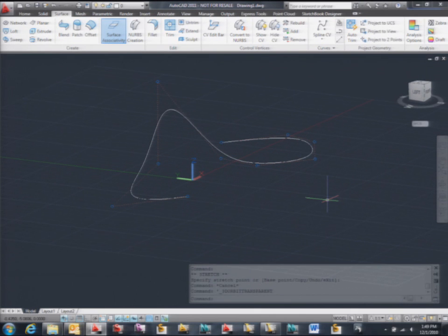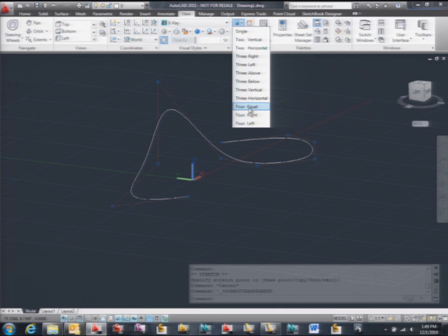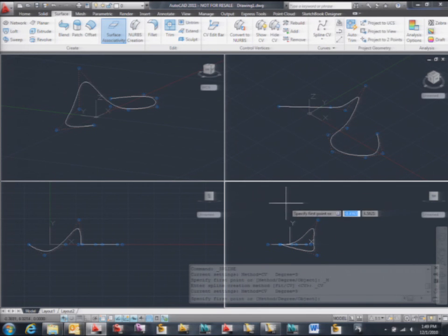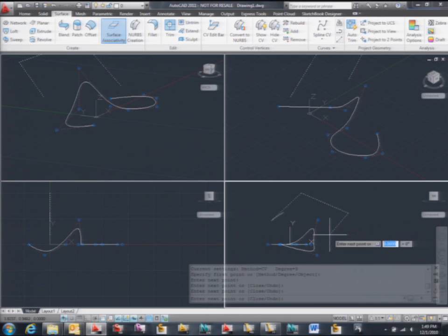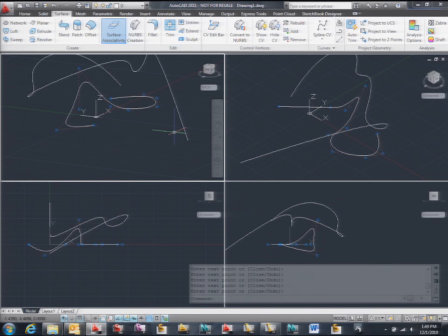And here's a trick that you may or may not know. Let me go to 4 views, right? And sometimes you may need to do that. I mean, you may want to have a top view, a left view, and a couple of perspective views, right? So I don't know if you knew. Maybe you did, and I'm being just stupid, but you tell me. You can start working on this viewport, and then just by clicking once on another viewport, you can continue the command on this other one or wherever else you need to do it. Right? So you have that kind of control.